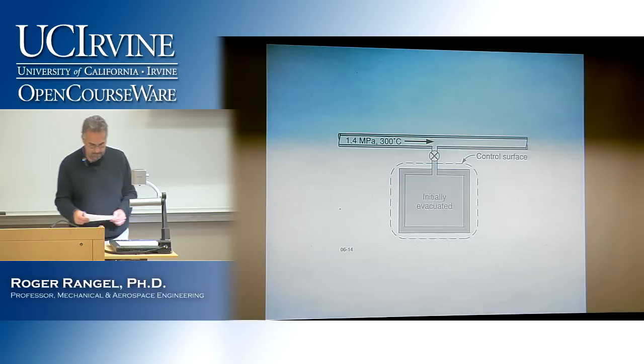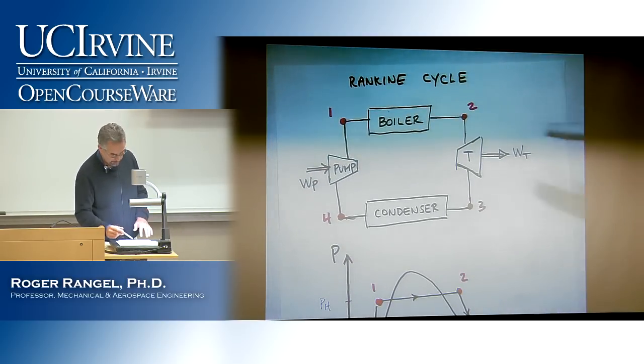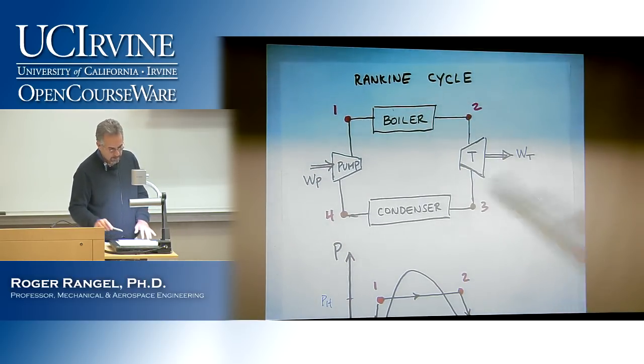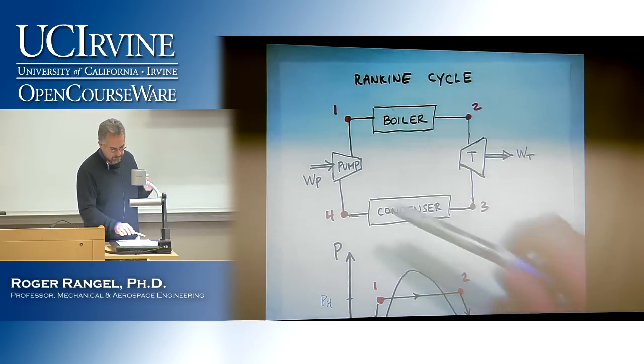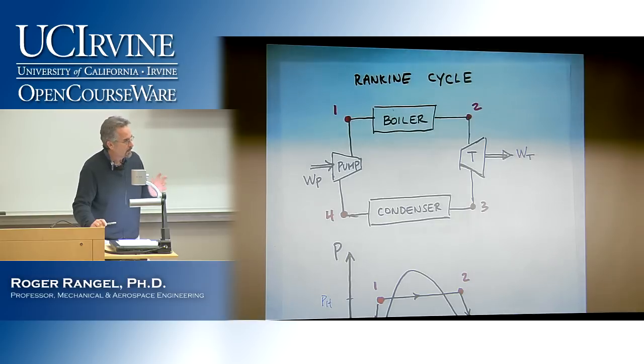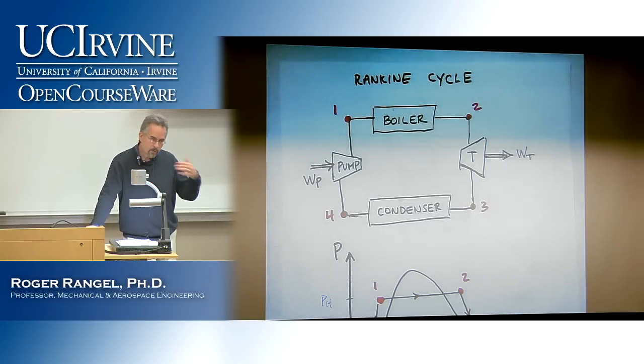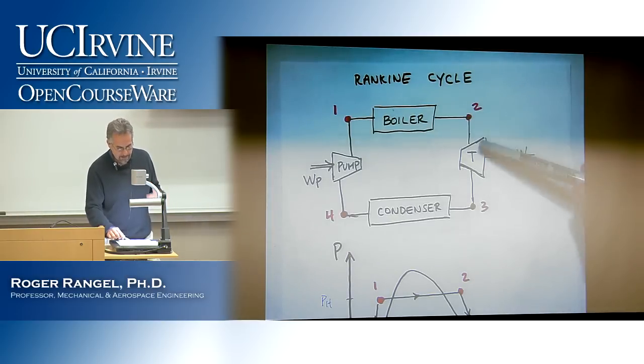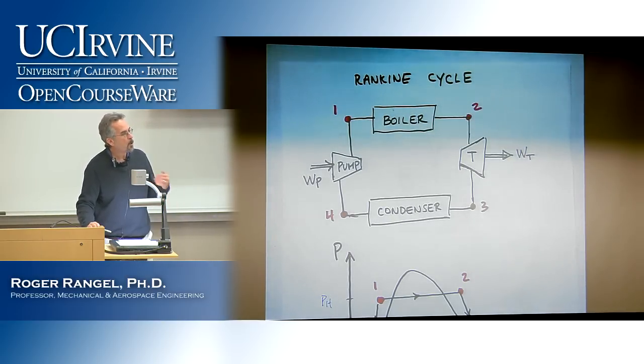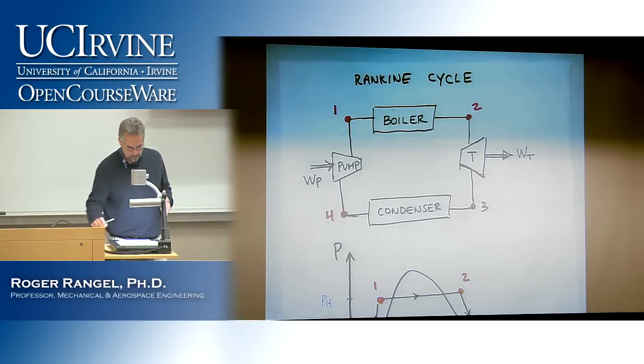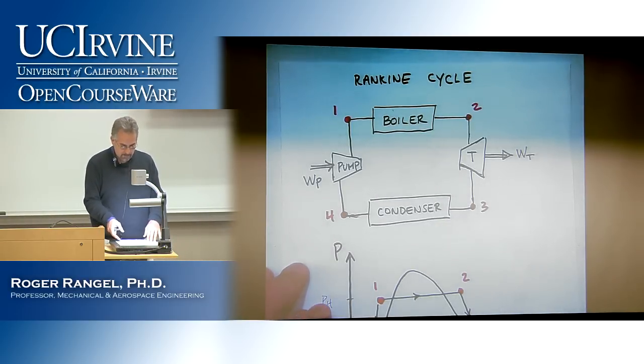Problems like this one we were just looking at, for example, take this turbine, we will look at them when the turbine is operated in the so-called steady state conditions. That is, the turbine or the condenser, the pump or the boiler, or whatever the device is, is operating in steady conditions. That means it's continuously running at some speed. If it's the turbine, it's rotating at some speed. And the fluid is coming in at the inlet port and coming out at the outlet port, always at that same continuous rate. Those are the so-called steady state problems.